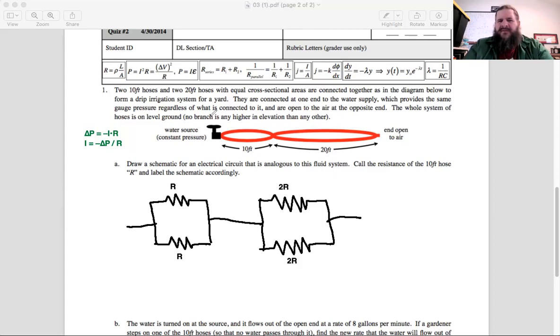And what's really the big difference between those? What's the difference between the faucet and the open air that we care about in the Bernoulli equation? Yeah, there's a difference in pressure. Presumably the faucet is high pressure, and the atmosphere is low pressure, specifically 1 atmosphere. So you create high pressure in the faucet to cause fluid to flow from the high pressure zone to the low pressure zone.